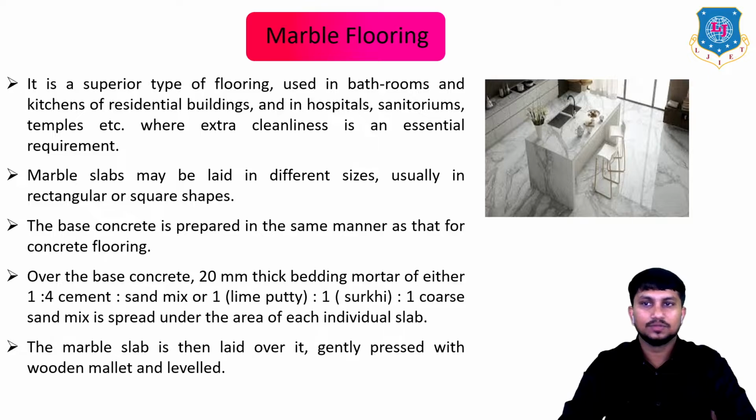Next is marble flooring. It is a superior type of flooring used in bathroom, kitchen of a residential building and in hospitals, sanatoriums, temples, etc., where extra cleanliness is an essential requirement. Marble slabs may be laid in different sizes, usually in rectangular or square shapes. The base concrete is prepared in the same manner as that for concrete flooring.